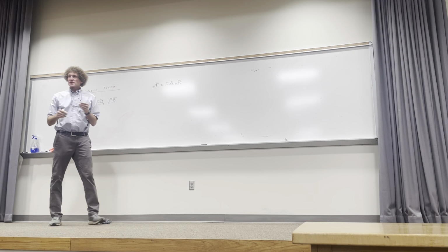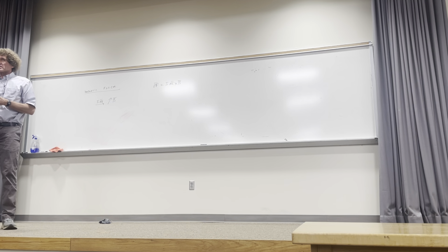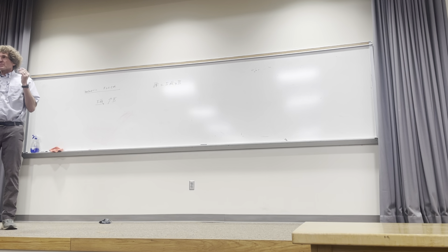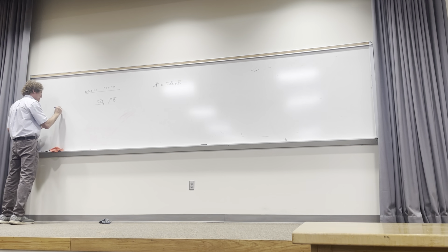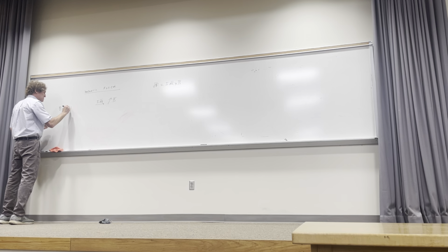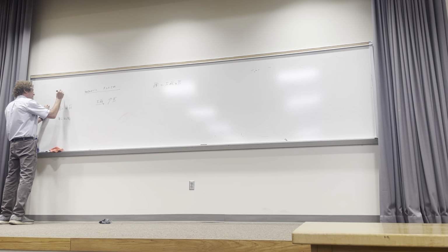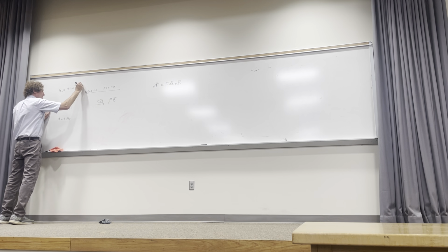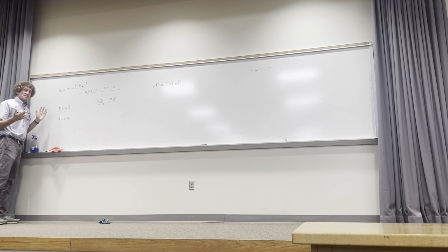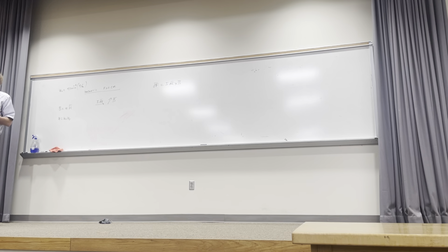Now that's sort of a statement of fact. It's based on experimental observation. So the B field, remember, is equal to mu H. And here, mu is equal to mu 0 times mu relative. And mu 0 is 4 pi times 10 to the minus 7th henries per meter. It's a constant, right? Just like epsilon.